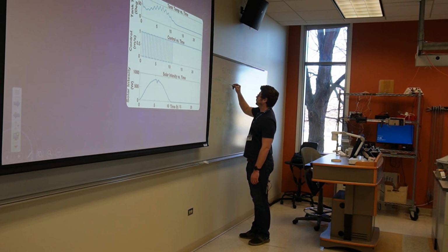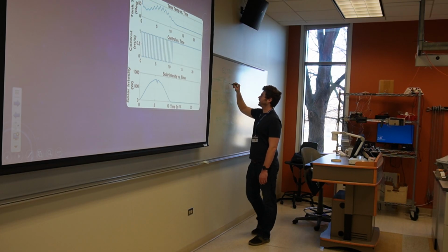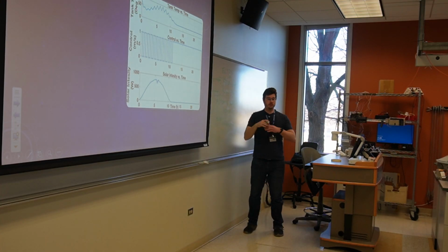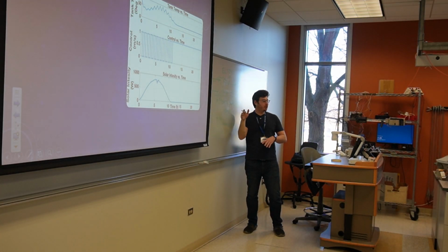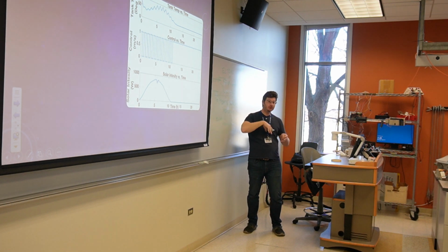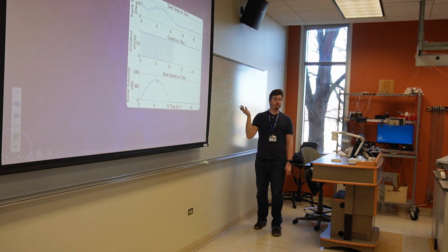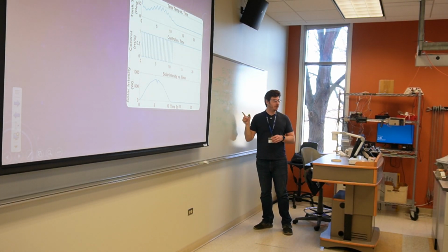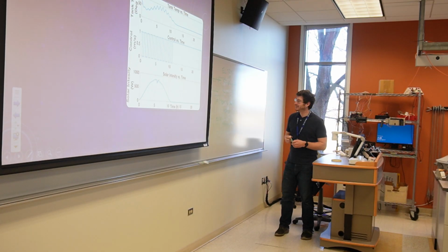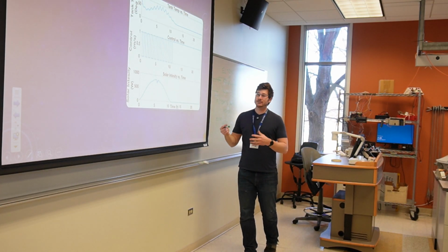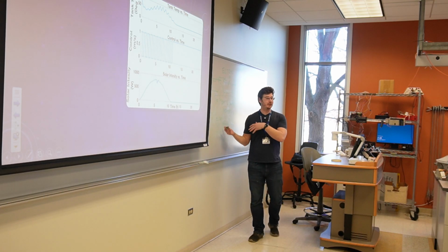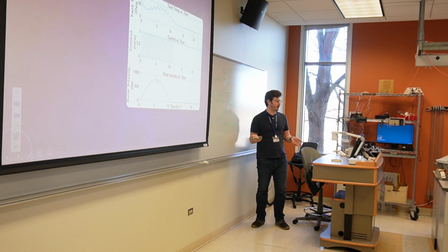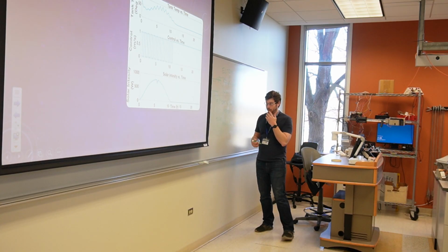every time it crosses this threshold, our relay will click, it'll trigger. So if our relay is clicking like 100 times per second because it's really close to our set point and it's like, oh, we're 0.1 degrees C over, I'm gonna turn on the relay. Oh, we're 0.1 under, I'm gonna turn off the relay. It might last 2 days before you burn out that device. And certainly annoy the crap out of anyone who hears the clicking all day as you're trying to regulate the temperature in the room, okay? With MOSFETs and silent devices, that might not matter as much. You might be able to get away with a bang bang, but it's just implications of why this isn't the end all be all and why we can do better.